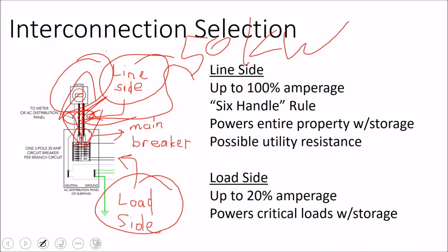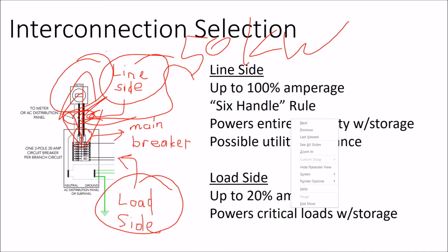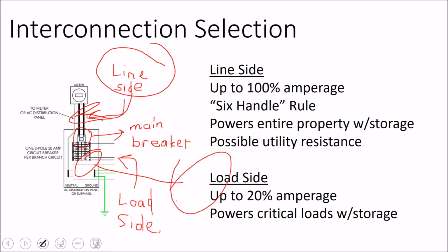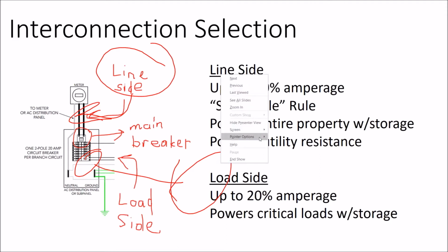So if you've already done a line side connection, or it's just more convenient, it's not the end of the day to do a load side connection. Sometimes it's going to be better, if you don't want to have batteries, to tie in your solar array on the line side and then have a generator do a critical load panel, or tie in. You could also tie in here.